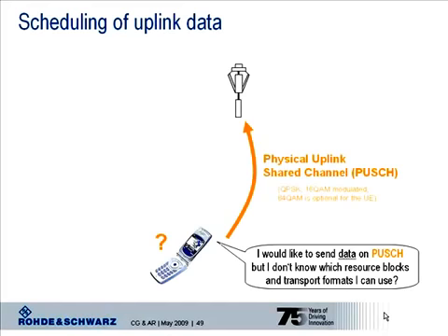As said, data are sent by the UE on the physical uplink shared channel. This channel, again as the name implies, is shared between all UEs in the radio cell. That means the UEs are sharing the bandwidth of, for example, 20 MHz, equals 100 resource blocks, when the radio cell is configured for that bandwidth. A UE would get resource blocks assigned where QPSK, 16 QAM or 64 QAM can be used as modulation schemes. Note that 64 QAM is an optional modulation scheme in the uplink.